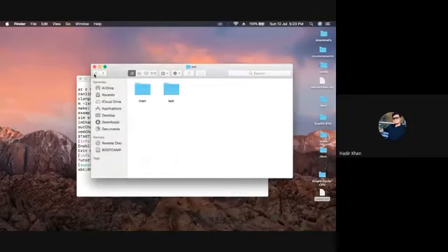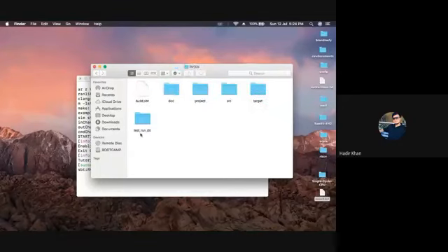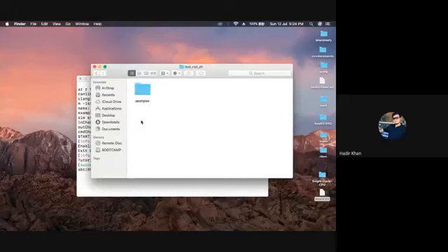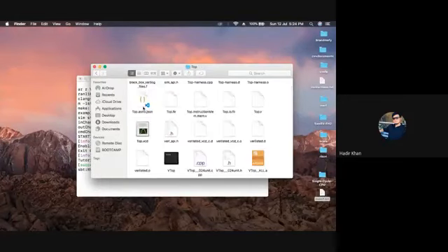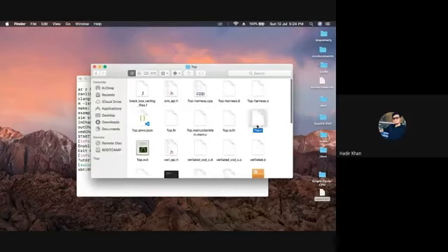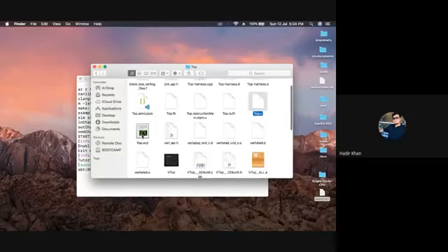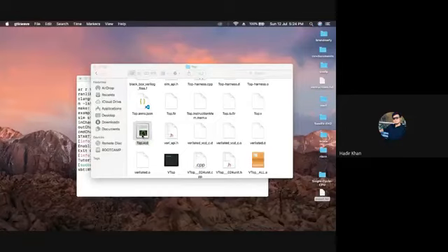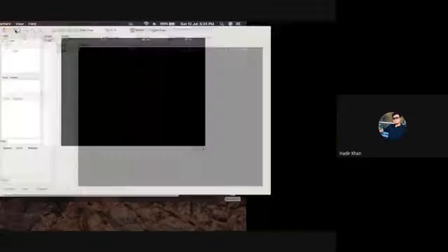So what we're going to do is, all right, into the RV32i folder, we'll go into the test_run_dir, examples, top, because this is the module that we generated. As you can see, we have this top.v Verilog file as well, which later Zishan is going to use to show you guys how we emulated this on the FPGA as well. And then we have the VCD file as well, so that right now, without using the FPGAs, we can just have a quick look and simulate what's going on in the processor.